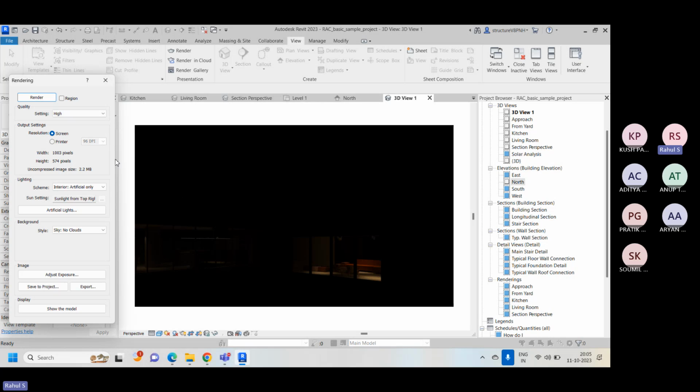When you are rendering, for that particular material the texture will not appear in your rendered images. If you have something like a textured wall paint on the exterior surface, and this wall paint is not supported by your render studio, in that scenario that particular wall will not showcase the realistic view in your rendered image. It will look like a normal white or generic material. So whichever errors you may face, you need to work on them and fix them, and only then completely render the images.